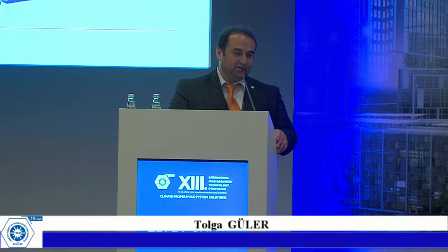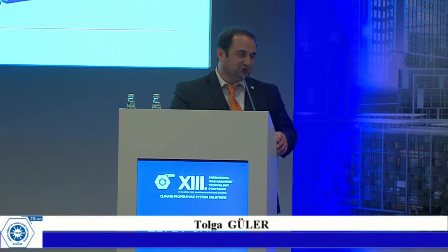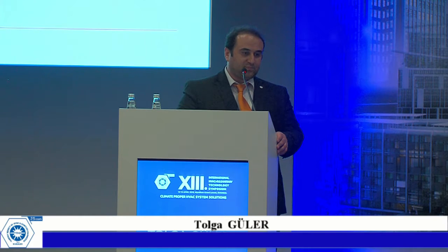And you are seeing the packaged air handling unit in the picture, and there are two coils, two filters, and there is a heat exchanger. Also, two fans are here, and these are not static. They are rotating in the simulation, and there is a mixture damper in the simulation here, and we can do this with porous medium definition.